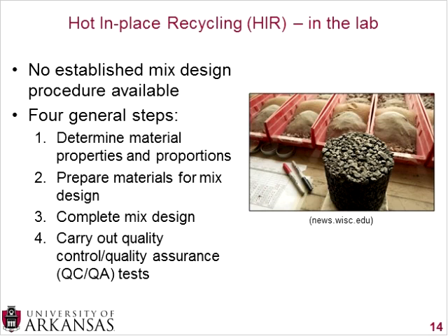Then you need to prepare your materials for a mix design. You need to take them out of the field into the lab, and then you need to break them down into testable sizes in a method similar to what you would see in the field, so you're able to do step 3, which is completing the mix design itself. And then when you're done with the mix design, you can carry out your quality control or your quality assurance tests.